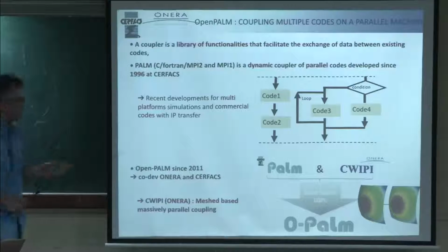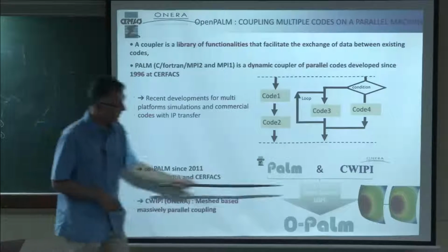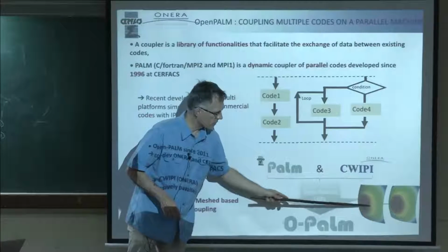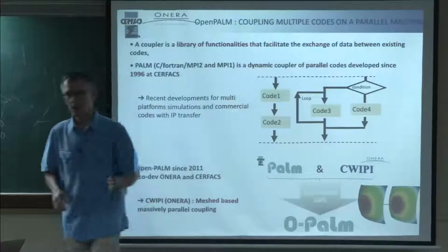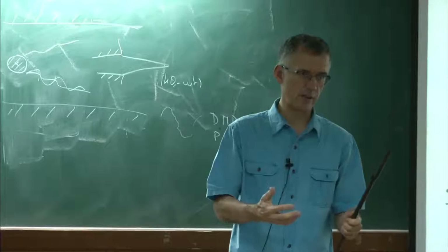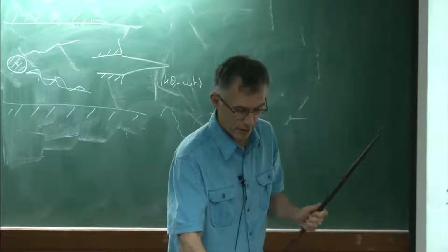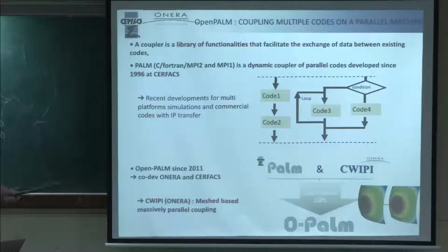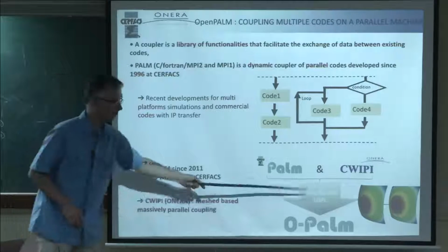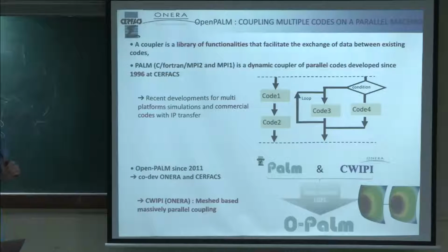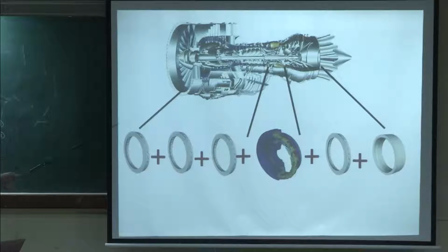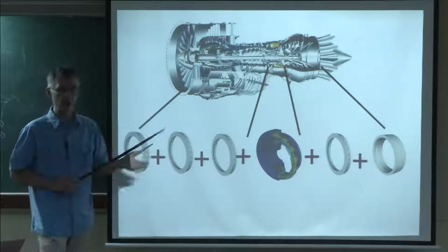Of course, I did not discuss that too much. An important part of that is the interpolation of one grid to the other. That's a tricky part. You want it to be conservative. You want it to be fast and high order. That's done in the solver. And the license of that is LGPL, for those of you who know open source code.